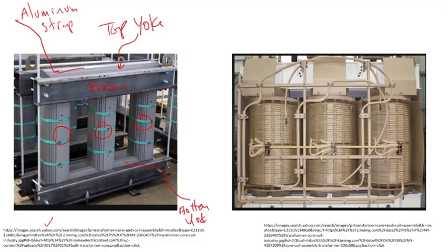So the core is grounded. The frame also might be grounded as well. The frame might be grounded internally, or it might be brought out to a bushing. Typically for large power transformers, you would have 2 bushings, one for core ground and one for the frame.